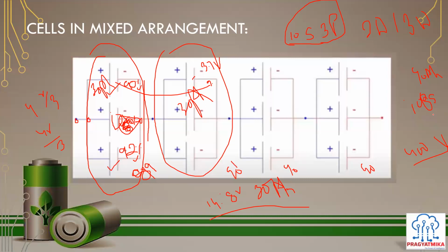Actually, when you purchase a BMS, they don't have a rating of 3P or 4P. They are sold as a 10S BMS, 12S BMS, 14S BMS. It means that this number of cells are connected in series. Now, how do we take a reference for the P connections? They have the current rating: peak current, average current, and minimum current, based on which we select them.